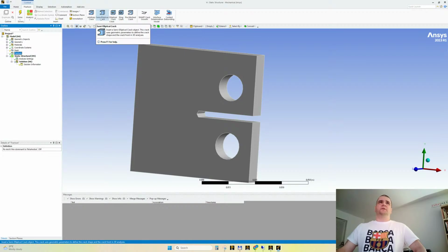What we are going to use today, this one is interesting because here we can apply a surface body. Just imagine like a coin, but it should be a surface body to have a 0 millimeter thickness, and we can apply this one anywhere on the part, and in principle, this small surface that we apply will propagate a crack. In principle, it's not the topic for today. It will be for a later stream. What we're doing today is this one. It's called pre-mesh crack.